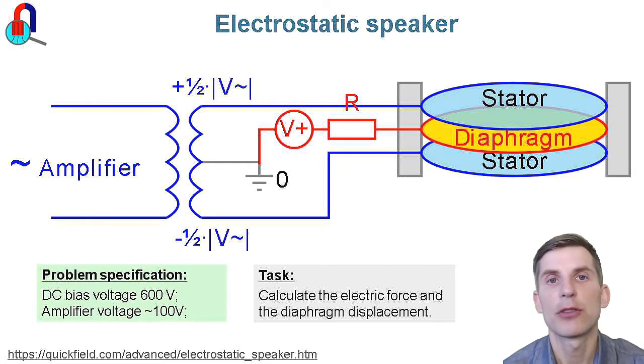First, I am going to simulate the electrostatic problem. I will apply voltages and calculate the electrostatic force. Then I am going to pass the electric forces distribution from the electric problem to the stress analysis problem. In the stress analysis problem, I will calculate the diaphragm deformation.